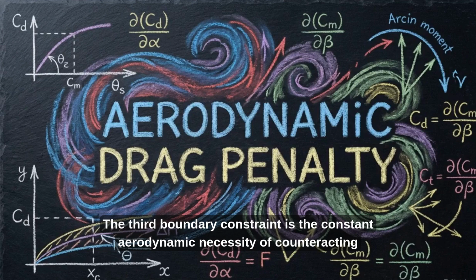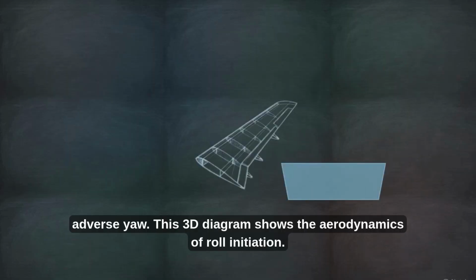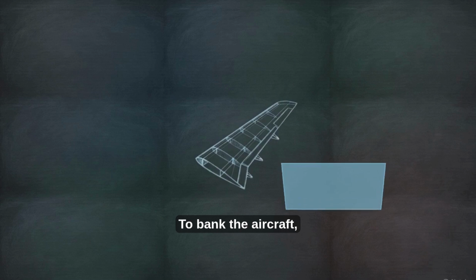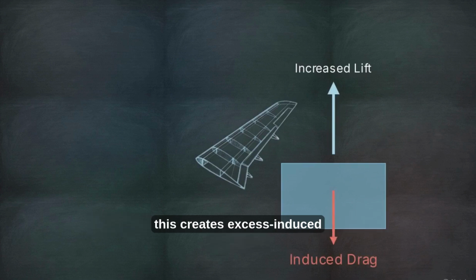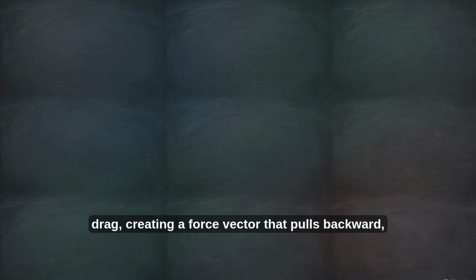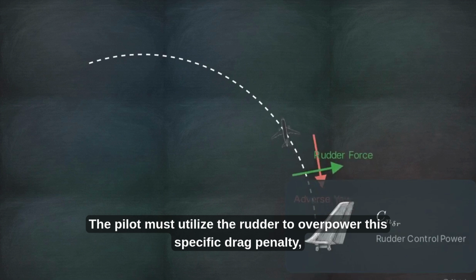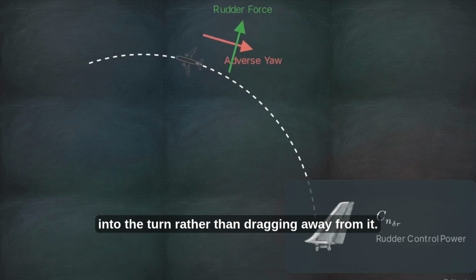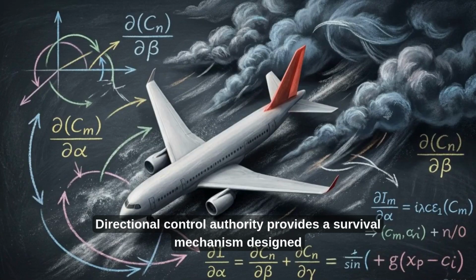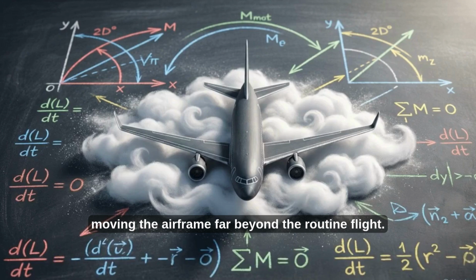The third boundary constraint is the constant aerodynamic necessity of counteracting adverse yaw. This 3D diagram shows the aerodynamics of roll initiation. To bank the aircraft, the aileron on the rising wing deflects downward, increasing lift. However, this creates excess induced drag, creating a force vector that pulls backward, directly opposing the direction of the turn. The pilot must utilize the rudder to overpower this specific drag penalty, forcing the nose to track smoothly into the turn rather than dragging away from it. Directional control authority provides a survival mechanism designed to brute force the aircraft through extreme asymmetric regimes, moving the airframe far beyond the needs of routine flight.